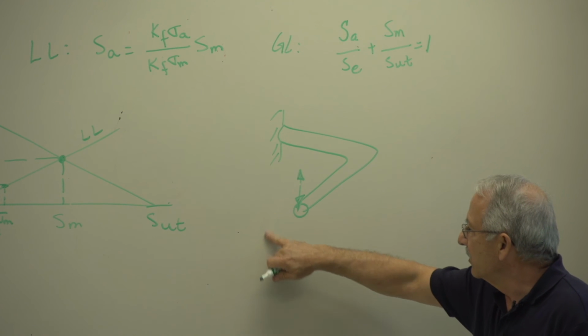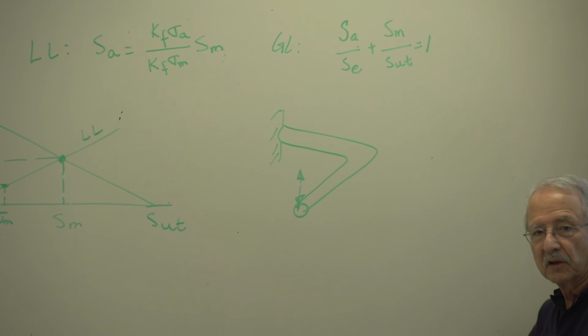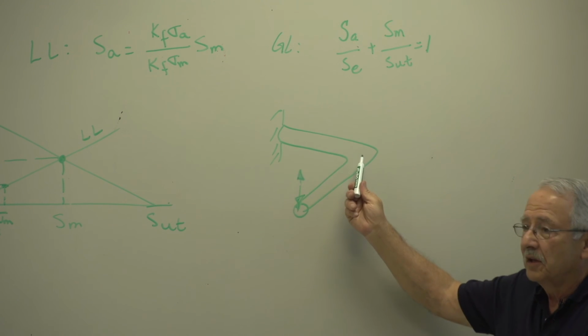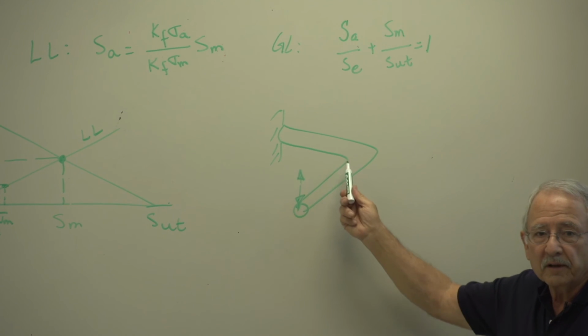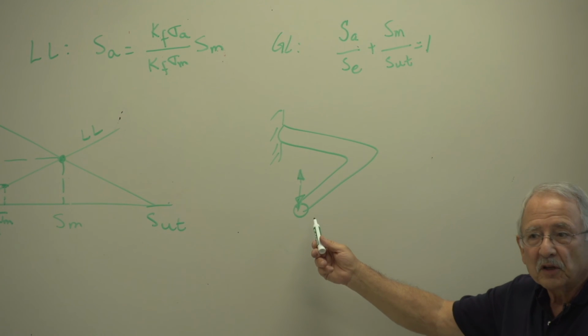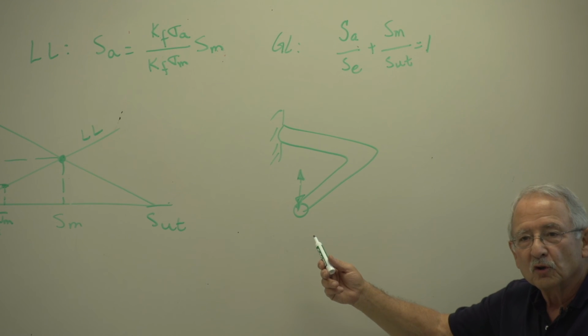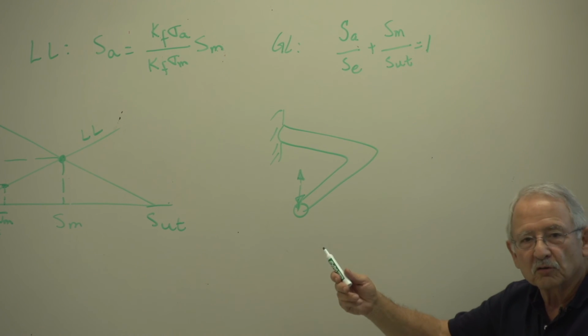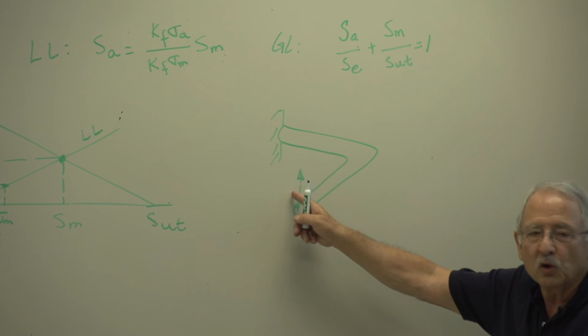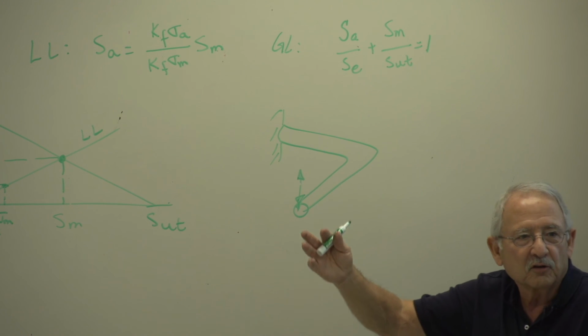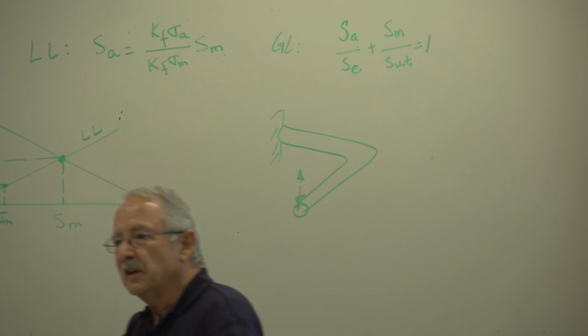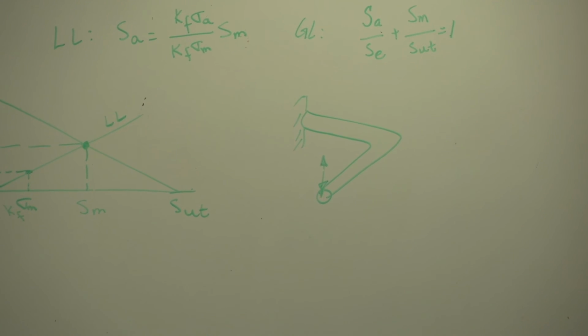I don't have to write anything on it. This is self-explanatory. Take a look at this. This is under bending and torsion, right? Whenever the bending stress is maximum, the torsion is maximum at that time too. Whenever it's zero, torsion is zero too, because that means that this load is not there. The load is there, they're all there, and they vary with that load. This is called varying in phase.